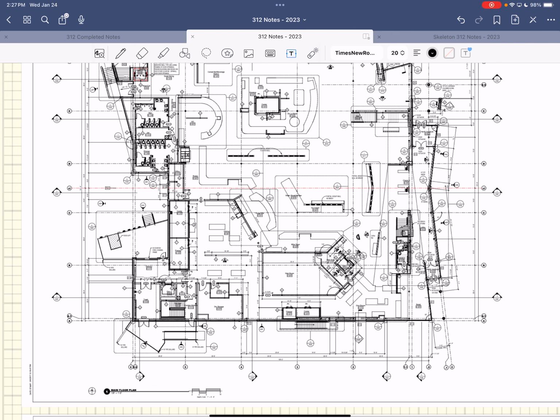And then I'm going to decide what my floor plan is going to look like, based on which way I'm going to have my columns, layout, how am I going to have my beams, how am I going to have my girders, where are my joists going to be. You come in, and so that's where you get started.